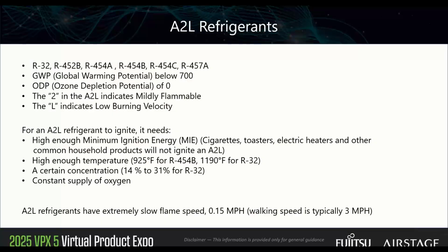But for any A2L refrigerant to ignite, 4 conditions have to be met. It needs a high enough minimum ignition energy, MIE. Cigarettes, toasters, electric heaters, and other common household products will not ignite an A2L. It also needs a high enough temperature: for R454B, it's 925 degrees.